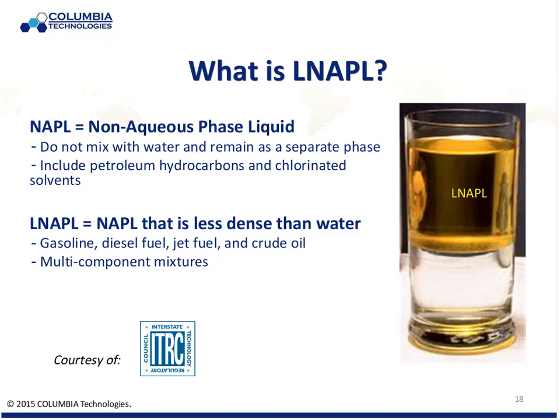As hard as it is to believe, in 2015 we still have a fundamental misconception about what LNAPL does in the subsurface, and a lot of people still think we're in this LNAPL float. So we have oil floating on top of water, and the fact is that we have an air, NAPL, water continuum or mixture like this. Sitting on the desktop here, oil will float in my glass of water. But if we take that into the subsurface and start acting on that oil, we're going to get a different type of relationship.